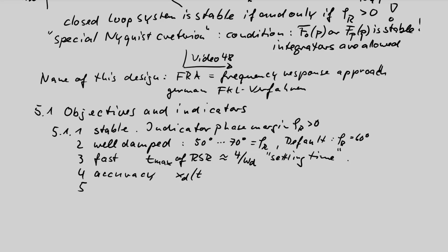If I wait long enough for the oscillations to come to rest, the control difference for large times is an indicator. If I can calculate this control difference with values coming out of the open loop Bode plot, which is available for all these investigations, then this is a very good help.